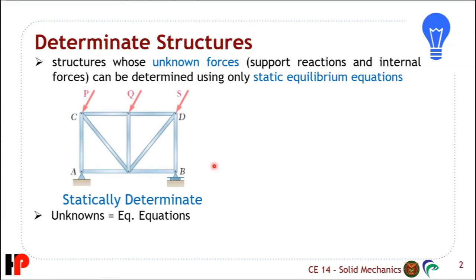All four bar forces, as in a truss, right? And reactions can be determined using equilibrium equations only. So you don't need any other compatibility equation. Now, just by looking at it, you should be able to determine that it is completely constrained, meaning that it will not move under regular or basic loading, like as shown in this slide. It is completely constrained because under the normal loads, it will not collapse, nor will it move, translate, or rotate.